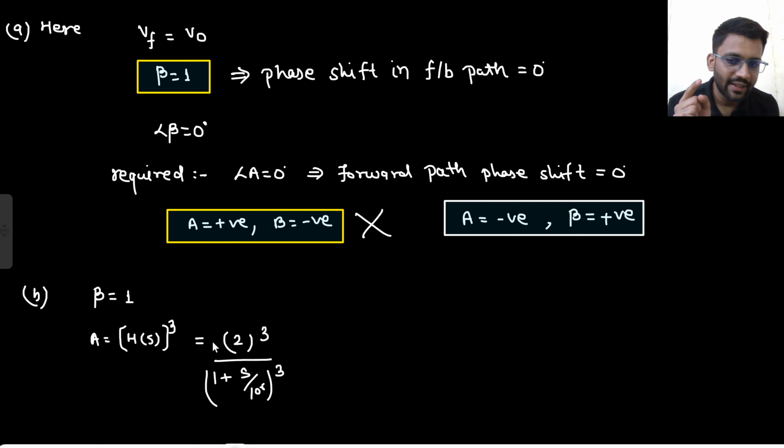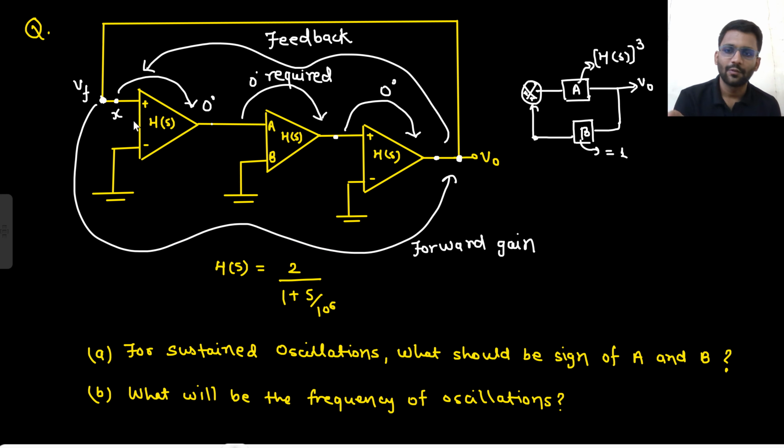So here we will have a negative sign, right? Here we will have a negative sign because from here to here the gain would have been h of s into x. Now there is a negative sign, like this is negative and this is 0. So what will be the gain here? H of s minus h of s into h of s. So minus h of s square into x. Are you getting this point or not?